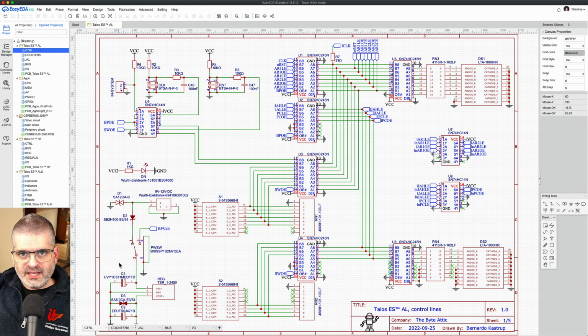If you've made the board before, I know of at least one of you who has made the ALU card, it's very easy to replace it. You can just use your soldering iron to heat up the 2 pins of the capacitor, and you pull it out from the other side. Then you can use some solder braid using your soldering iron at say 370 degrees Celsius. You can use some good quality solder braid to clean the holes from solder and reopen them.